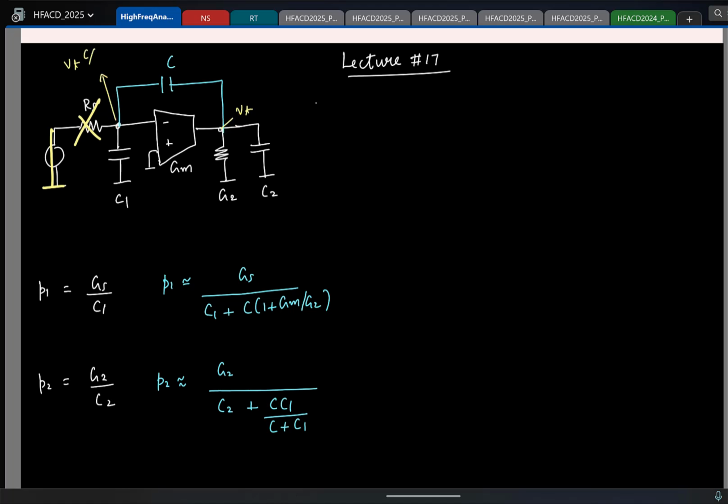C by C1 plus C. So what can you say about the current we draw here? The voltage here is this much, so the current that GM draws is proportional to that. This will also produce a real part of a current when you apply a test voltage. So that will also contribute to the total conductance, and that value is essentially GM.